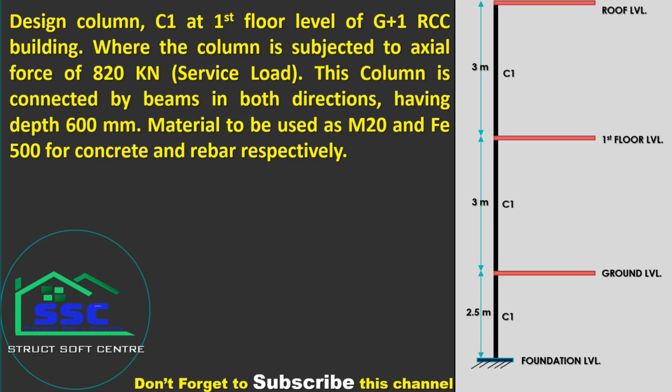But this column is connected by beams in both directions having a depth of 600 mm. What is the application and need of this data? The depth of the beam, we will discuss it later. The materials to be used for designing this column are M20 and Fe500 for the concrete and rebars respectively.